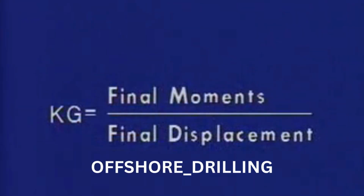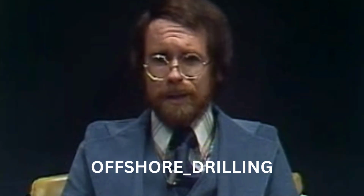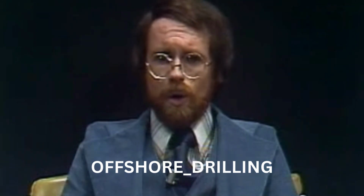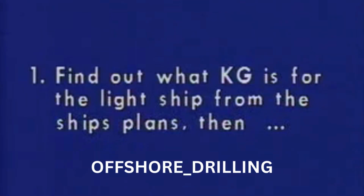Here's the formula that we're going to use. Kg, or the height of the center of gravity after loading or unloading, is equal to the final moments divided by the final displacement. Now let's go over the steps in finding kg after loading or discharging cargo. First, we will have to find out what kg is for the light or empty ship from the ship's plans.